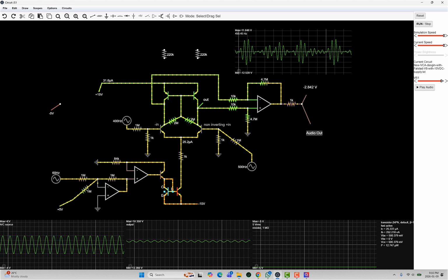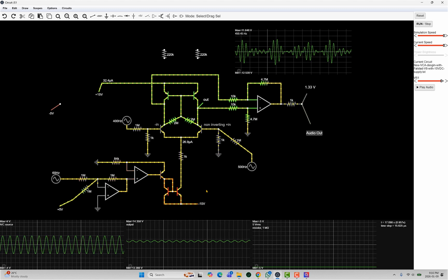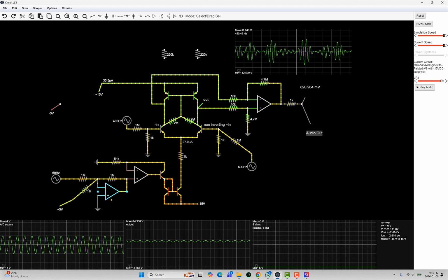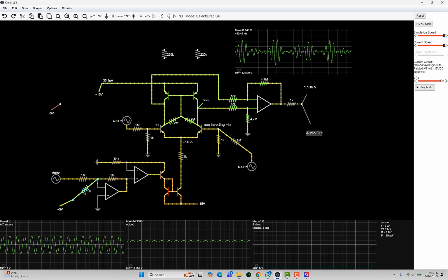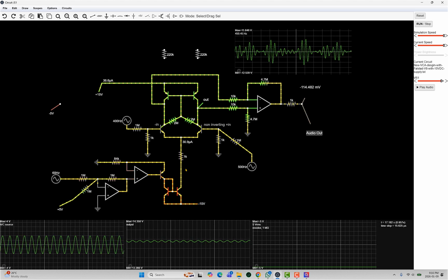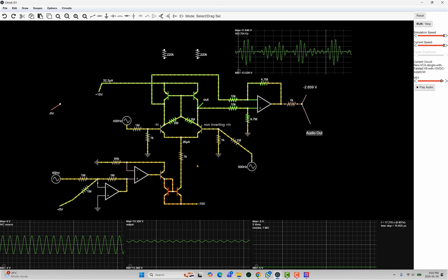These ones might be less critical, but it might be a good starting point to get matched ones if you're not sure. Or just pay attention to the current right here and see if it's linear when you come in, because that's the main thing: if you double the voltage, this doubles. If you can get that effect, then you could probably calibrate it by just changing some resistors here in the gain.